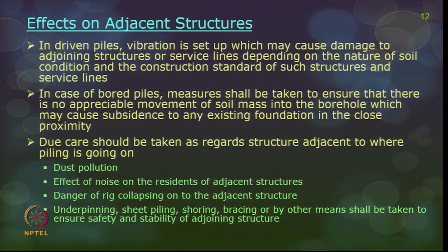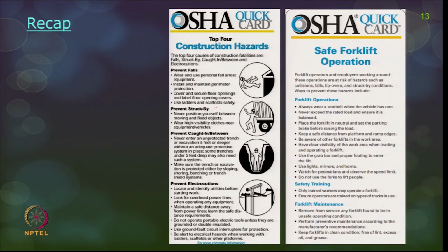So, due care should be taken primarily because of dust pollution, noise for the residents of the adjacent structures, and the danger of the rig collapsing onto the adjacent structure. So, underpinning, sheet piling, shoring or bracing, all these can be thought of as safety precautions to protect the adjacent structure.